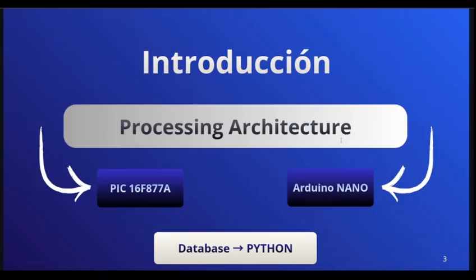The Arduino delegates a very specific task, screen control. A PIC16F877A microcontroller functions as a slave coprocessor. Its sole job is to receive data via the I2C protocol and display it on the LCD.